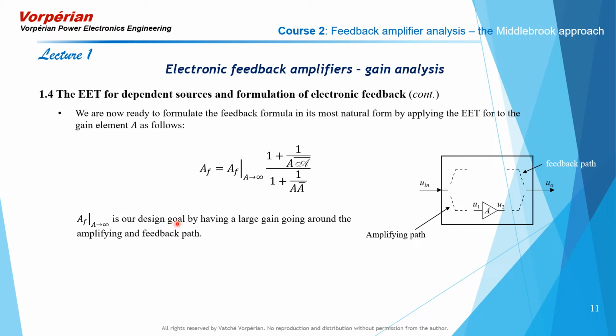In real life, we don't have infinite gain amplifiers, and the closest thing that we can get to one is an op-amp. So why don't you think of your first op-amp circuit that you learned? A resistor R2 connected from the output to the inverting terminal, and another resistor R1 connected from the inverting terminal to an input source Vin, with the non-inverting terminal grounded. You learned the gain of that circuit was minus R2 over R1, and the gain of the op-amp never got into the picture because you assumed it was infinite. But the gain is never infinite, and this is the correction factor that accompanies the ideal closed loop gain.